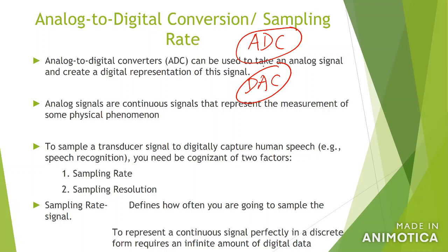Because computer systems are digital circuits, digital devices. But a lot of real signals like sound and pictures are analog signals. So to make sure that the digital device can process analog signals, you have to convert analog signals to digital. So that's why you need ADC.